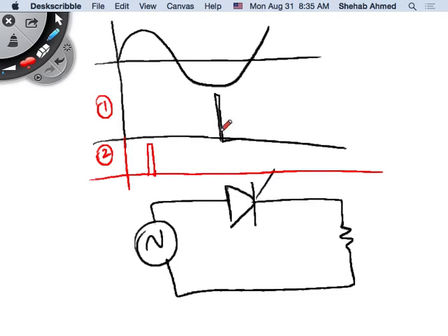If you put a diode after, so at the beginning, it's open circuit. So if it's open circuit, what does the output voltage here look like? If there's an open circuit here, this is open. What does the output voltage look like? 0. So it's 0 until here in the first case. And then what happens after that?